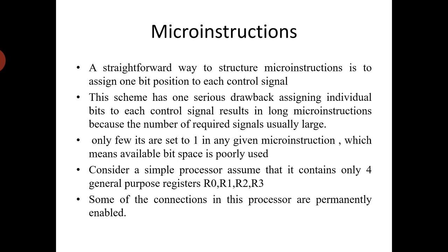And some of the connections in this processor are permanently enabled, such as the output of the instruction register to the decoding circuit, which is continuously enabled, and both the inputs of the ALU.